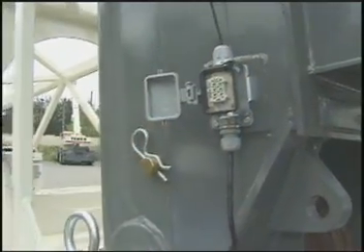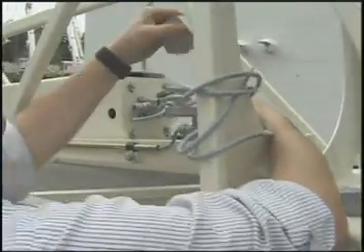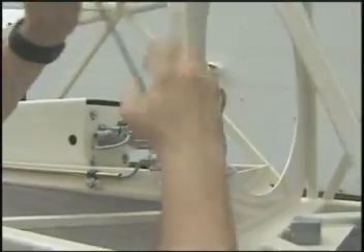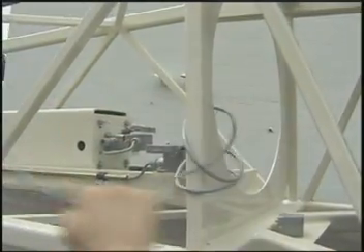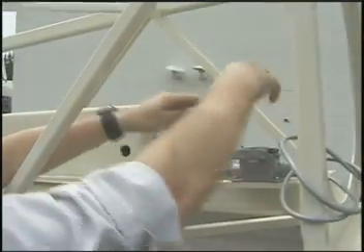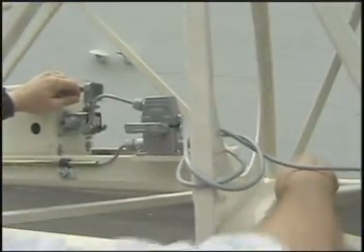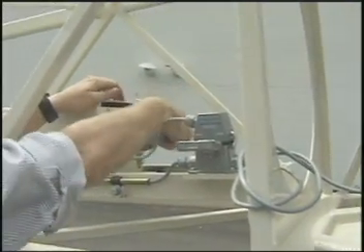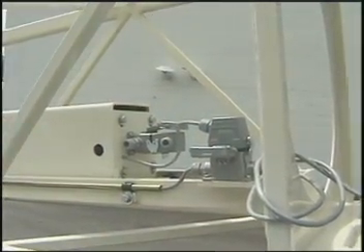Next, remove the dummy plug from the socket on the boom head. Take the plug from the main body of the jib and place it into the boom head socket. Run the plug from the stinger onto the main body of the jib, and finally, place the dummy plug into the socket on the stinger. The telejib is now ready to use.